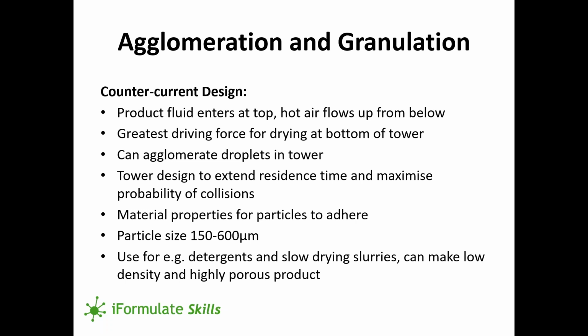By creating circulation forces for the droplets in the tower, you can get those droplets to collide with each other and to agglomerate as they dry in the tower. And the tower design needs to be such to extend the residence time and to maximize the probability of collisions of particles. You also need to be careful about your materials properties so that the particles adhere to each other and don't bounce off each other when they collide.